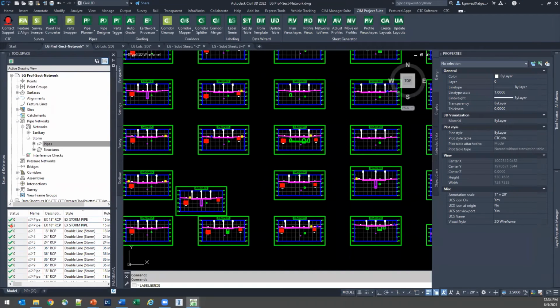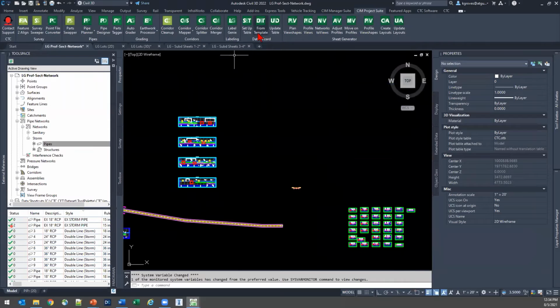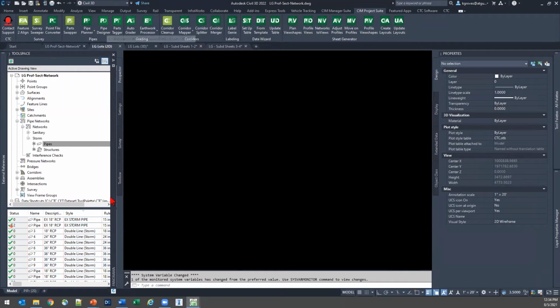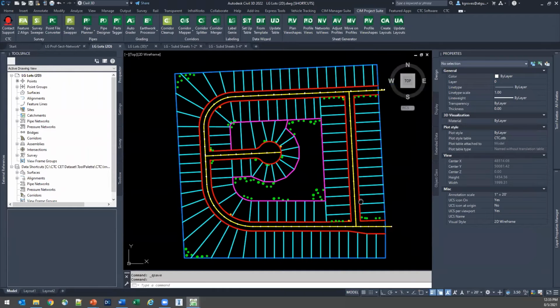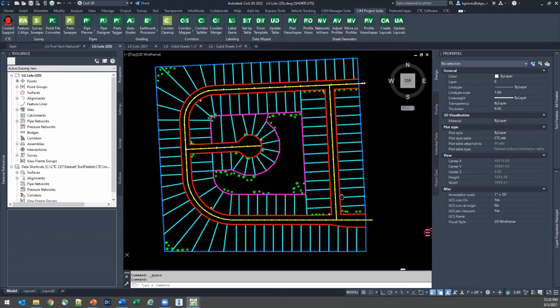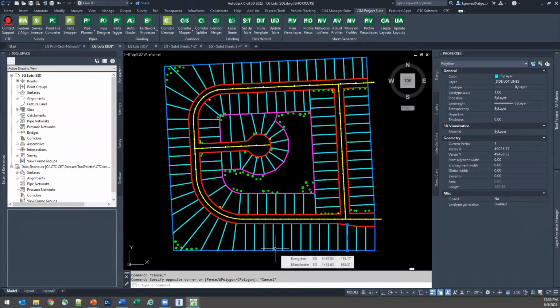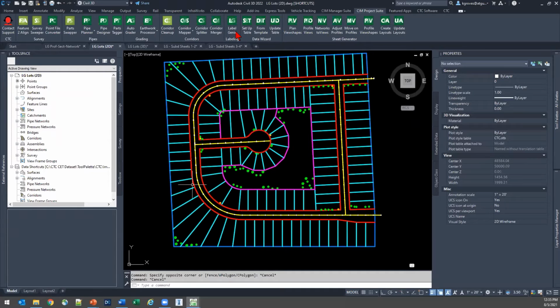So that's our plan view, that's our profile view, that's our pipe networks, that's our basic polyline and mtext type stuff. Let's move into a subdivision workflow though. Not everyone's using pipe networks, though I'd say it's one of the more universal tools inside Civil 3D. Now I want to use Label Genie to get my subdivision laid out. This is my 2D file. Maybe I'm surveying and I'm doing this as a plat toward the preliminary basis. Maybe I'm just marking out the geometrics plan for my lot. So I've got a lot of different situations I can deal with.